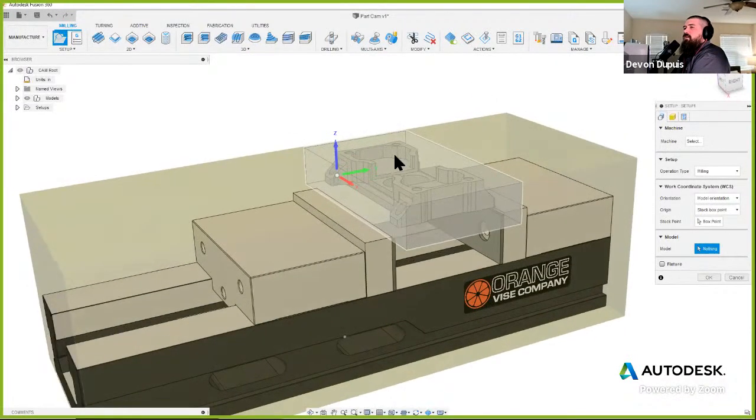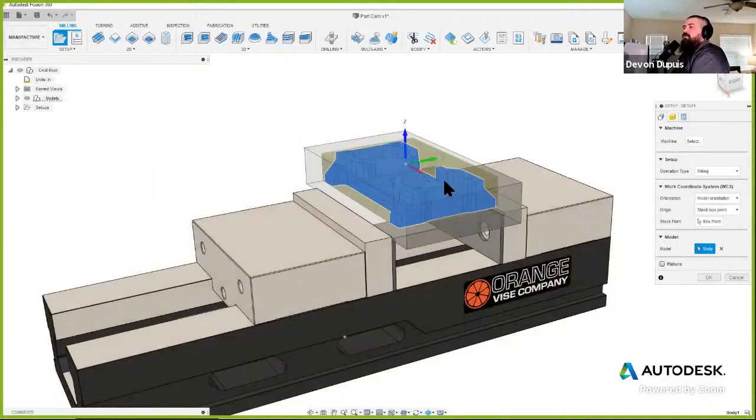Do that again. I can click and hold on this, and it'll pop up this little box here that'll let me kind of select through things. So if there's other faces or entities behind this, it'll also include them. So that's why I want to get a decent view. But I'm going to pick this body one because that's what I'm looking for. You can see that my stock mode here is set to a relative size box.